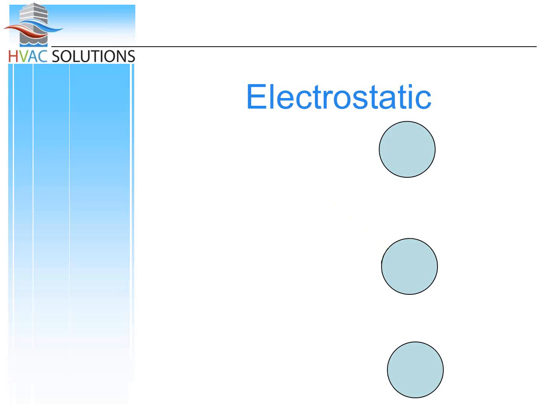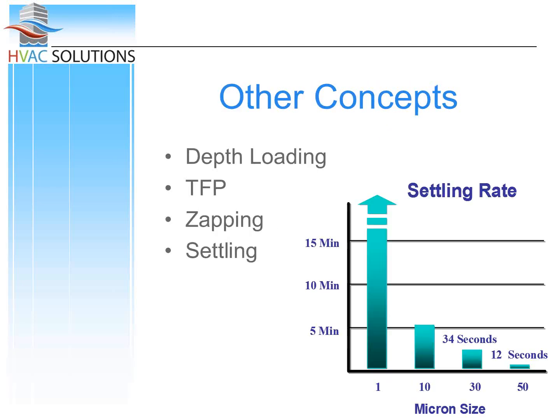As airflow is going through, it stops at the cardboard, but then slowly makes its way through those holes. And when we do that, we make filters more efficient. You will usually see this on HEPA type filters as a pre-filter. So the idea is you can change out the pre-filter every year or maybe every 6 months, and then you're changing out the HEPA filter every year to 2 years, depending on the system you have.